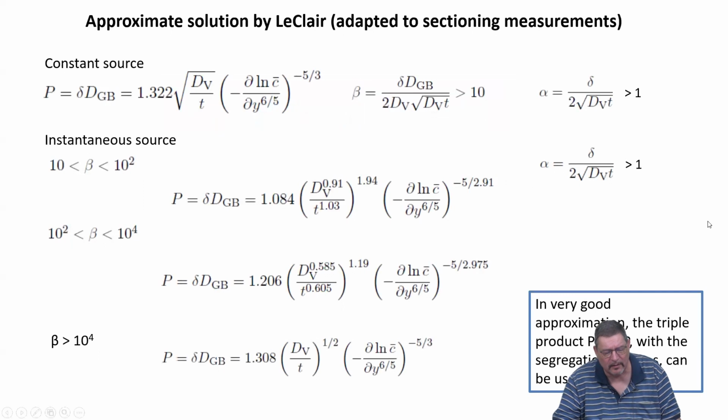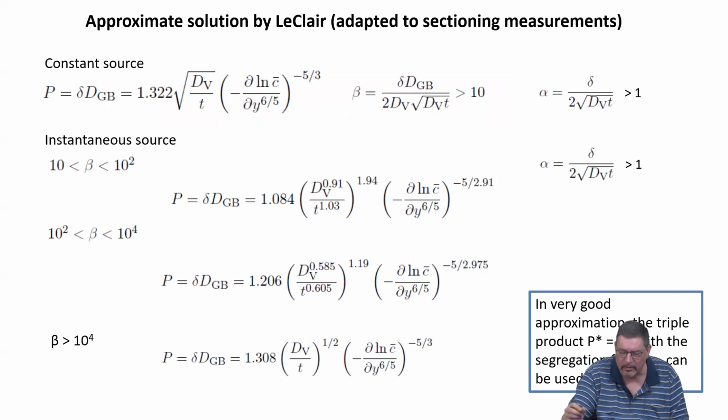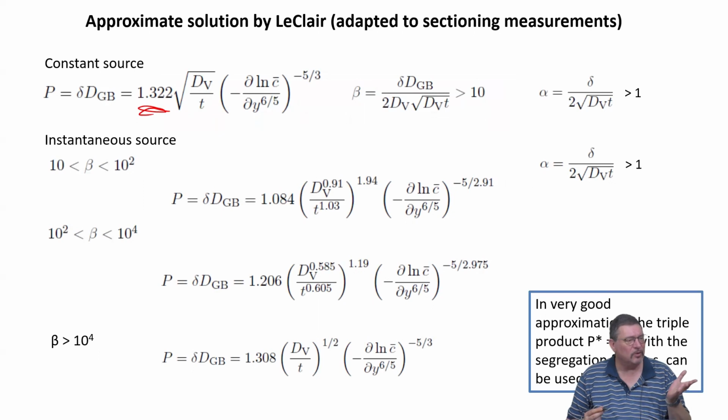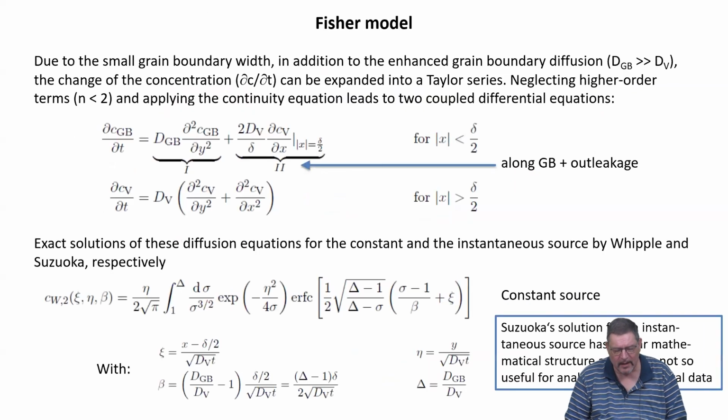You know, in these solutions, you get then only values which you can really determine, which are varying, like grain boundary thickness, volume, and grain boundary diffusion coefficient, time, and so on. But for example, something like this numerical value, this comes out of mapping the approximate solution onto the exact solution, and then this has no physical meaning, right? It's just a numerical fit parameter.